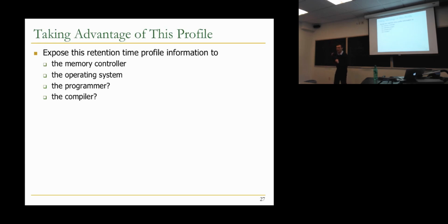At least we have a shot at verifying some of the hardware that we have today. The compiler could actually make use of this information also, again, on a specific system. If the compiler has a way of allocating data to a particular memory row, it can say, oh, this data doesn't need to be accessed beyond this time, so maybe I'll allocate it to a row that will retain the data without being refreshed. And people have proposed similar solutions. So this is an interesting thing to explore if you have this problem.